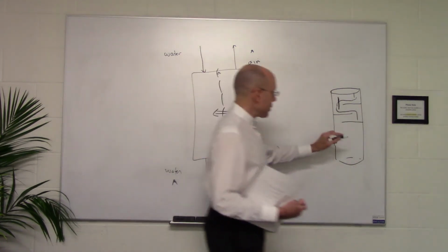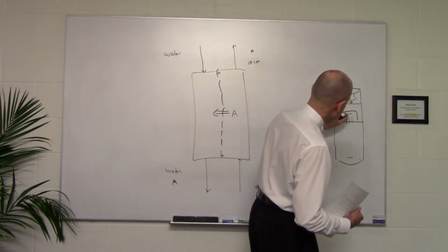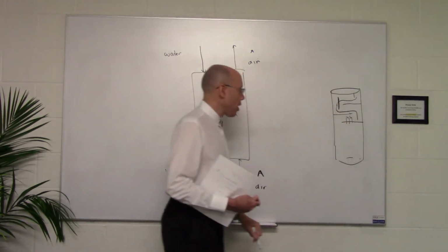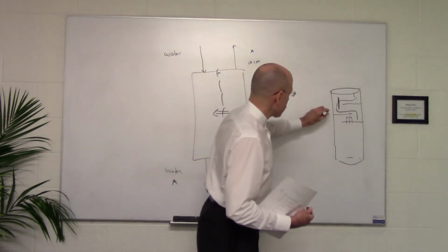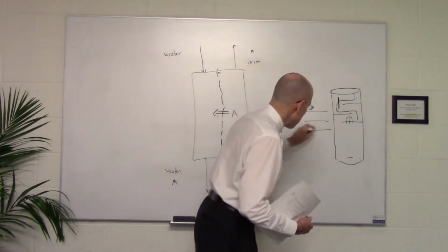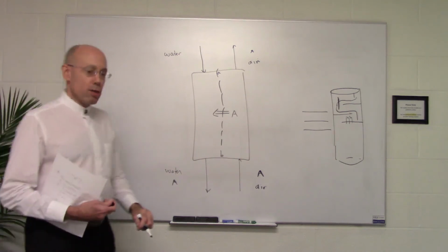And similarly, there's a gas phase which is going up in holes in these trays. And when it rises through the liquid, it makes bubbles, and there's lots of mixing and froth. But the key thing here is that the contact happens on individual trays. Tray number 1, tray number 2, tray number 3. And that's an inherently discrete process. And a lot of separations are done in that way.